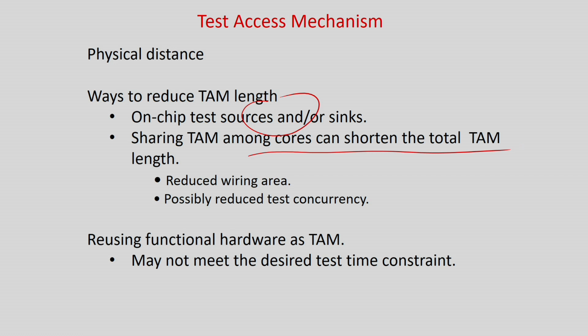So that is some shared bus. It will reduce the wiring area, of course, but it will lead to reduced test concurrency. What is a shared bus? A single TAM bus that multiple chips and multiple cores are accessing, so you can access only one core at a time. The concept is very similar to a single bus versus a multiple bus architecture.